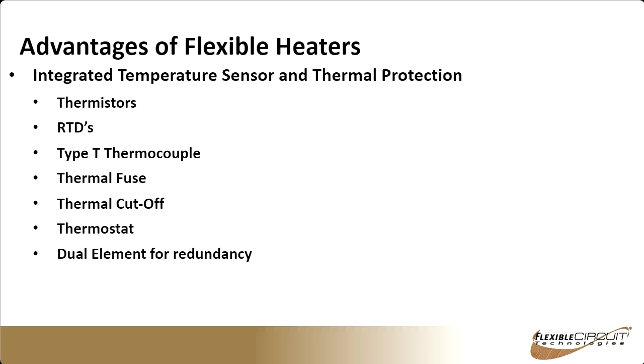And then the ability to integrate temperature sensors and thermal protection. So we can put thermistors on these heaters. Often these are just SMT type chips that get put on with pick and place. So it's very cost effective and efficient. We can put RTDs on them. You can create zones with the Type T thermocouples like I had discussed a little bit ago there.